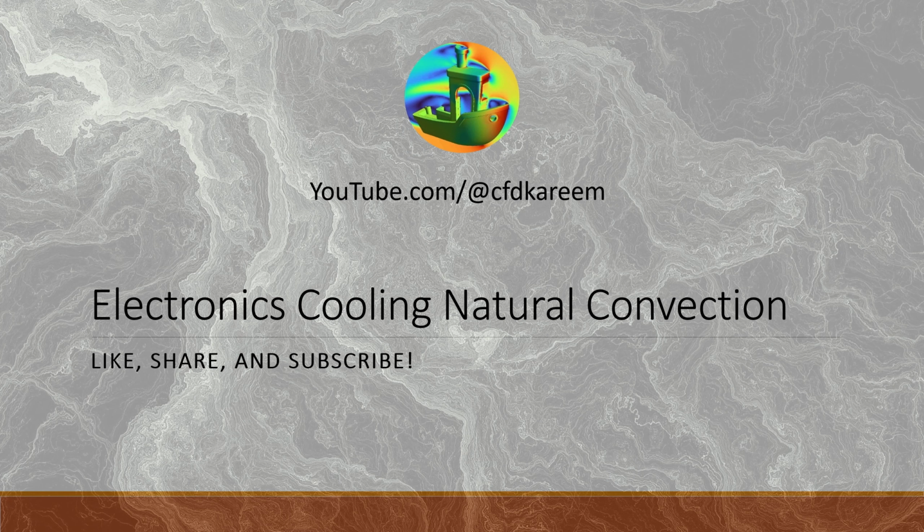So to wrap up, today we looked at a very simple 2D analysis of looking at electronics cooling using natural convection or passive cooling in a closed enclosure. Like I said before, you can easily extend this into 3 dimensions if you want to look at a more representative 3-dimensional geometry. Maybe add a heat sink, maybe try some different chip powers, so increasing that volumetric heating rate and seeing how that affects your simulation.